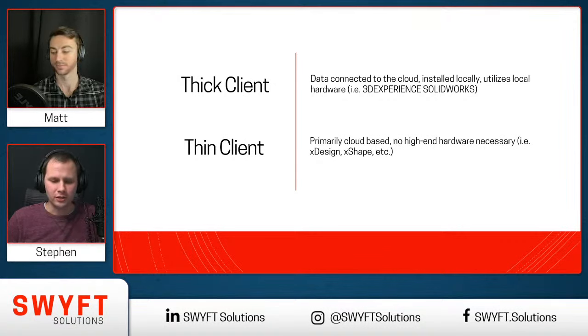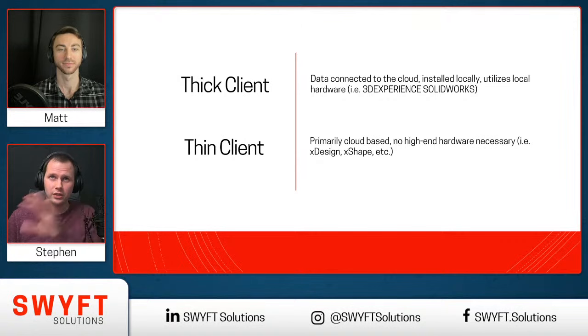So that's why it's still called SOLIDWORKS, and it's called SOLIDWORKS Connected. When you pulled up your model, you saw in the corner that it was still the SOLIDWORKS interface, but it said SOLIDWORKS Connected because you're still running SOLIDWORKS on your desktop, but the data is connected to the 3DEXPERIENCE. Absolutely. It's not like if your internet connection was to dip out, it would just shut down. However, you would not be able to save your data to the platform. You will need to reestablish the connection. You will need to have a connection to connect to the platform in the first place. Make sure that your data is connected.